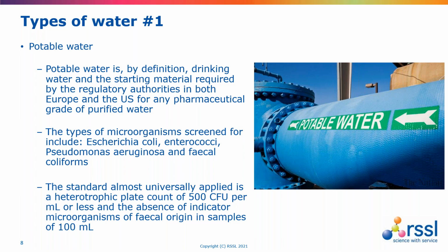And the water company, if there's a water company in place, will guarantee a certain level of testing. But if it's water in another part of the world drawn from a different source, then we should have an understanding of the level of pathogens such as E. coli and Pseudomonas aeruginosa as indicators of, say, fecal contamination and other organisms of concern.